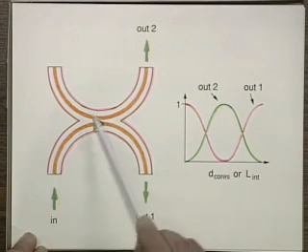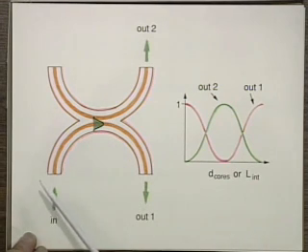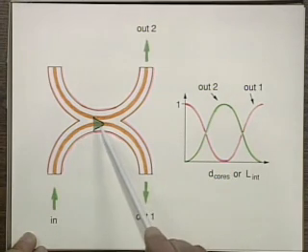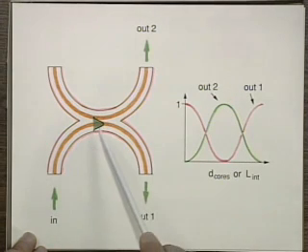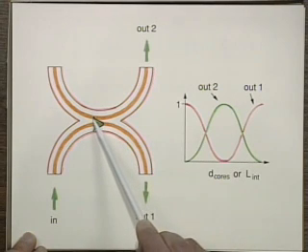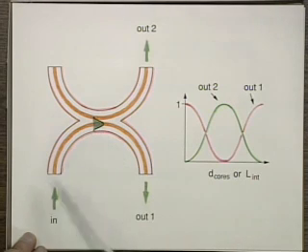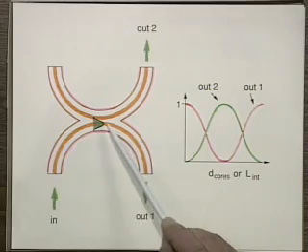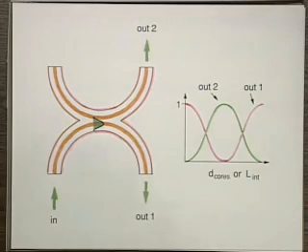And this is great because it's pretty low loss and is used, of course, all the time today. These couplers can be what we call the polished type or the fused type and so on. There are different types of couplers, but basically they work on that principle of bringing the two cores close enough together so that the evanescent wave, that little tail of the field distribution, will propagate in the other core and will drive the dipoles over there. All right. So that's basically the principle of a coupler.